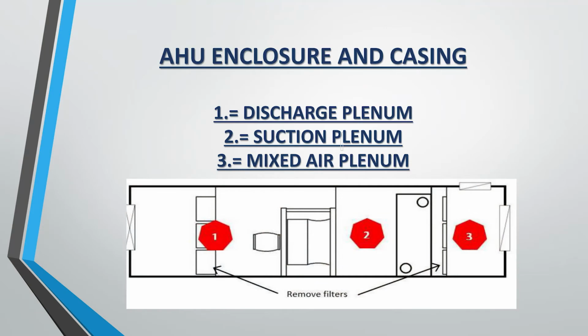So my idea was let's diminish it by 6 to 5 to 4 to see, if your allowable leakage on this thing is 300 CFM, let's see what it does. We're leaking at 500. Let's go to 4 inches or 5 inches, find out what it's leaking there. Will you be okay with, we're tested higher than what you say the operating will be, but we're going to be within your leakage tolerance.